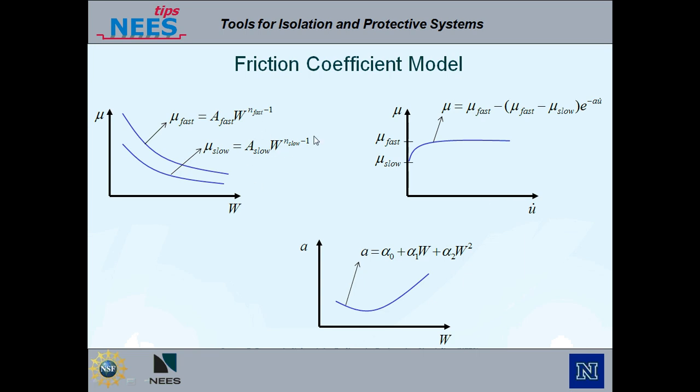As you can see, many parameters are required to define this general friction coefficient model. Because of that, detailed calibration of the friction coefficient is required. However, in this element, the user can also define simpler friction coefficient models such as constant friction coefficient model, vertical load independent friction coefficient model, or velocity independent friction coefficient model.